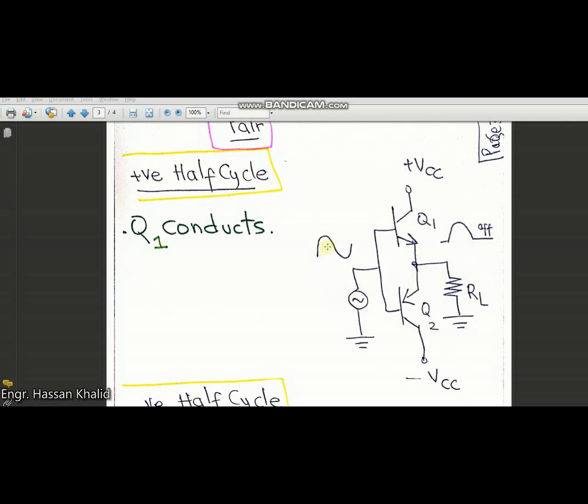When the positive cycle is initiated, one of the transistors, the Q1, is in the closed form. That means the switch becomes closed, whereas the Q2 is an open switch, and we receive the output signal whose amplitude is 0.7 volts less than the input signal that has been given, as I have also shown you in the class B type amplifying circuit.